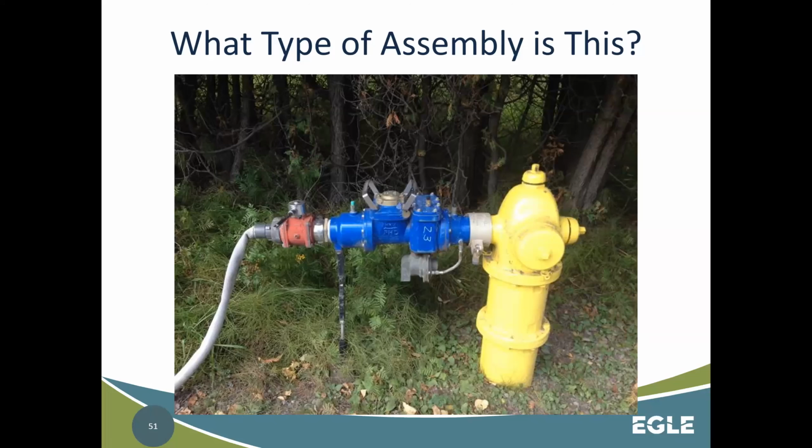From what I've been told, this is not approved in Michigan, evidently, though. I got told that by some guy from HydroCorp. I don't know exactly why. That's a Bob question. But this is an RPZ. It's a metered RPZ. Typically, if someone's going to fill off a hydrant, my guess is 99% of the cities out there have a requirement that they have to use a city-approved RPZ fill device off a hydrant.